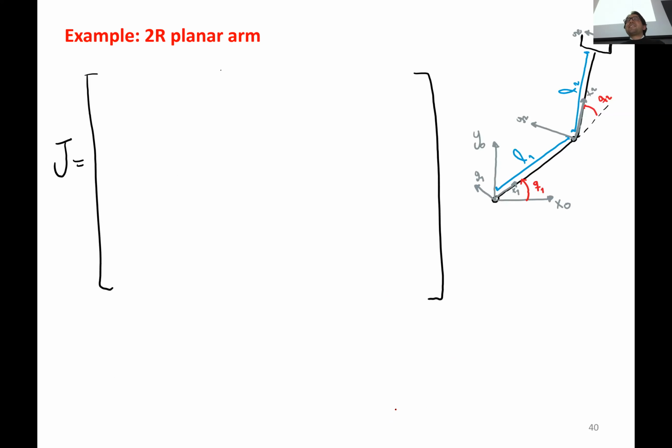So in the end, when you're doing the geometric Jacobian, the only thing that you need to know is the type of joint that you're dealing with. Then you just refer back to the expression, and it's very simple to derive this matrix. Of course, the more degrees of freedom your robot has, the more complex it becomes. For example, in our robot, the foot Jacobian, because we want to compute the position of the feet, is not super straightforward to derive by hand. So we use a library that does it for us.